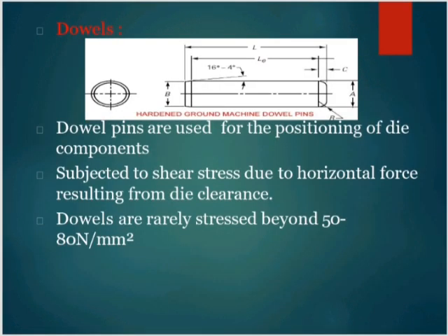Dowel pin. Dowel pins are used for positioning of the component. Developed shear stress is due to horizontal force resulting from die clearance. Dowels are rarely stressed beyond 50 to 80 Newton per millimeter square.